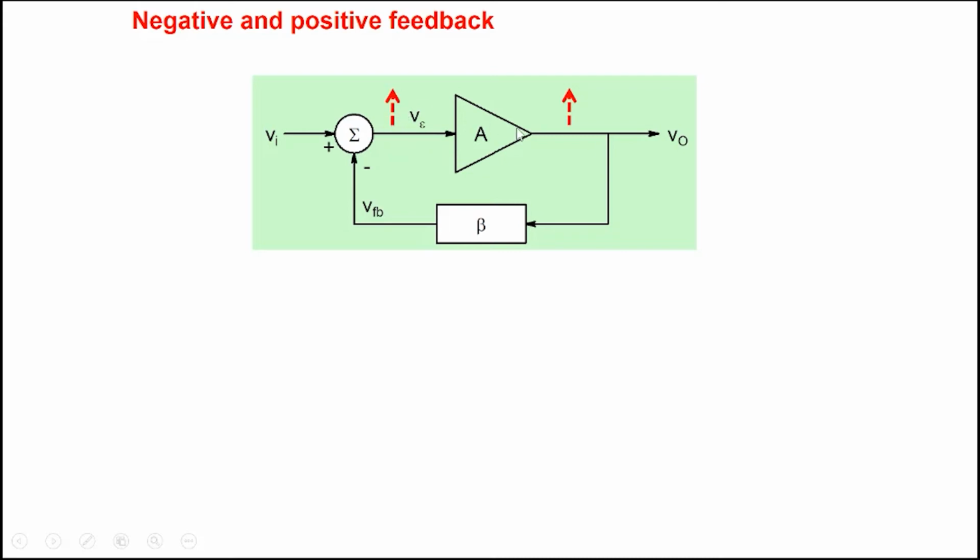So if I increase this, this voltage increases, but then this goes here and is subtracted from here. So what happens is this decreases here. That's what we mean by negative feedback: if this increases here, the output causes a counteraction to this particular change.